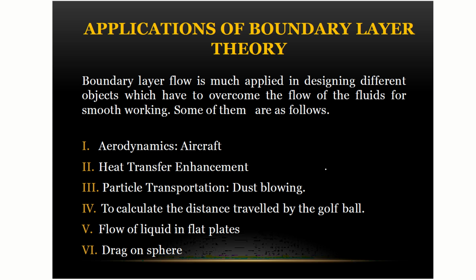This layer is where the effects of viscosity are significant, leading to a velocity gradient from the surface, that is from where the velocity is zero to the free stream. So understanding the boundary layer is very crucial in predicting drag and lift forces and separation of the flow, which affect the aircraft's performance, stability and efficiency.